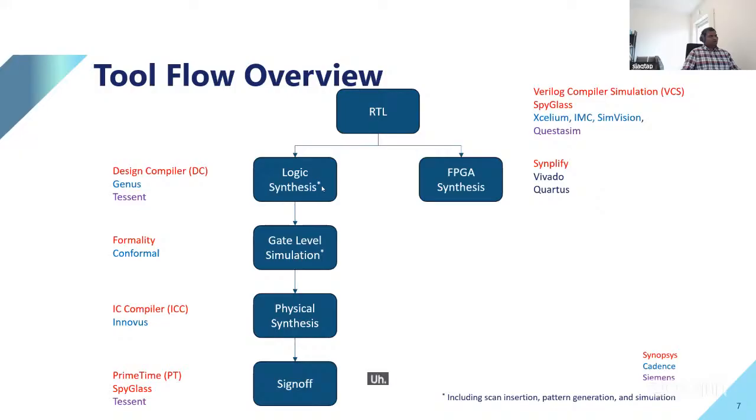The star which I have given here, basically at this point we perform not only logic synthesis, that means translating your logic into the gates, but we also perform scan insertion. Scan insertion is a test feature. Basically, after you get the chip, you want to verify that the chip is functionally working.